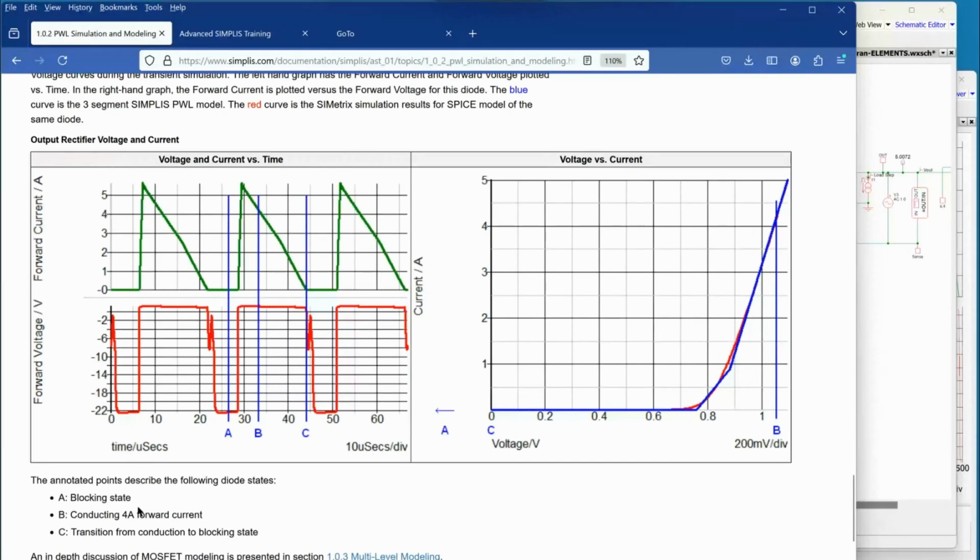So we're off and now we're turning on. How much time do we spend going from 0.7 volts to 1 volt, say? The answer is not much. It's the amount of time for this slope to go from here to here. That's how much time my model is potentially contributing noticeable error. It's very small.